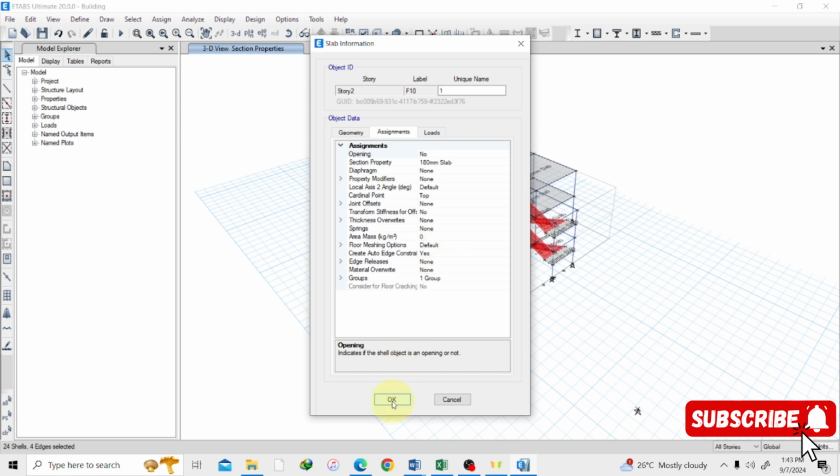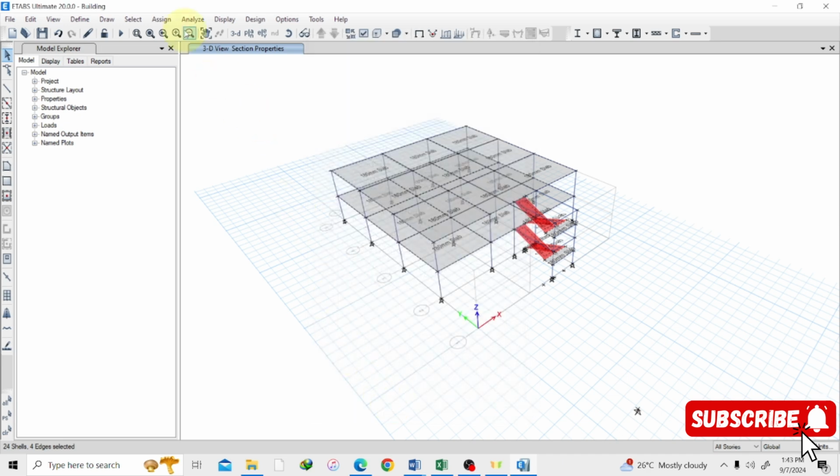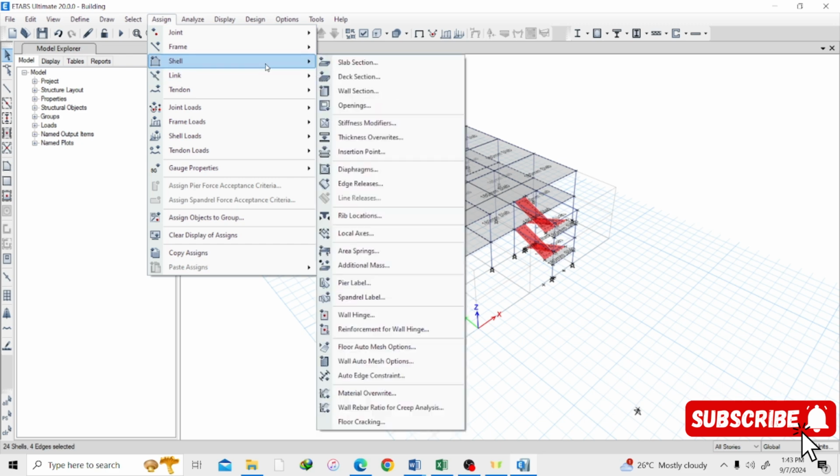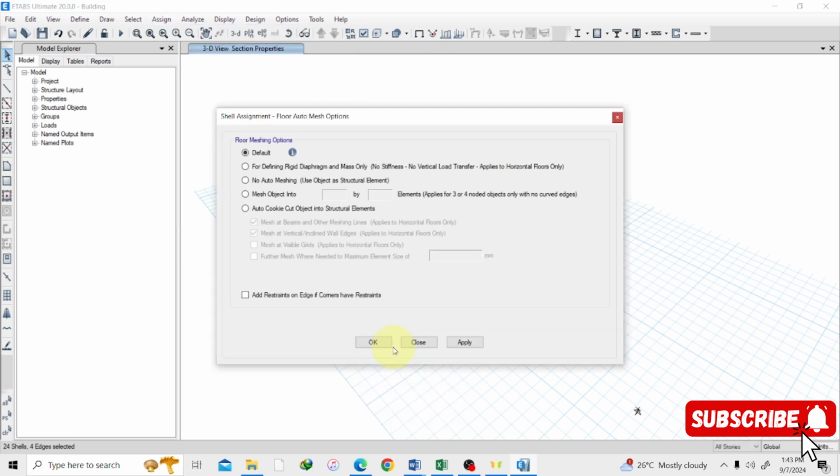So we just click on OK, then we go to Assign. You know that our slab is not a frame, it's a shell object. So we go to Shell, then Floor Auto Mesh, and click on this. So this is what appears here. This is the default that the ETABS app uses to mesh the slab. You can decide to stick to this default, but I will not really advise that.